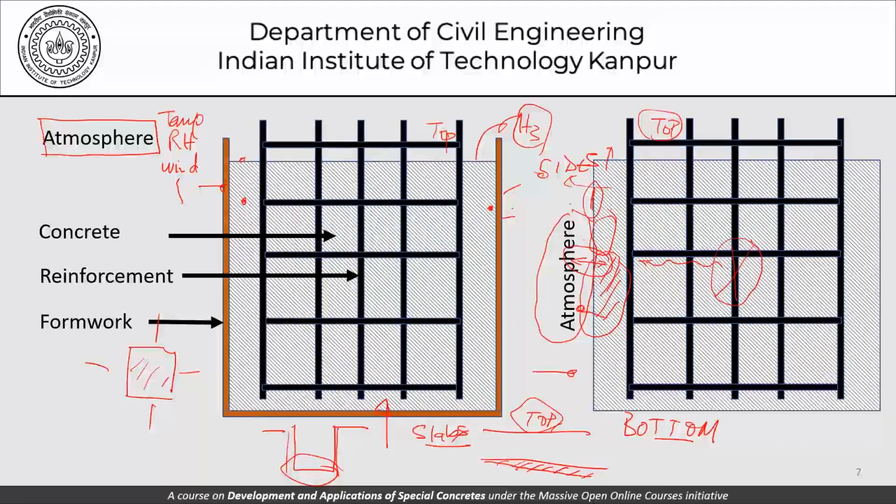The effort involved in curing, or the principle of curing, is basically to handle whatever goes on at the surface of concrete. We cannot do much about what goes on inside the concrete. The difference between the inside and the outside would be significant if the member thicknesses were large. If the member thicknesses were small, it will not matter so much.